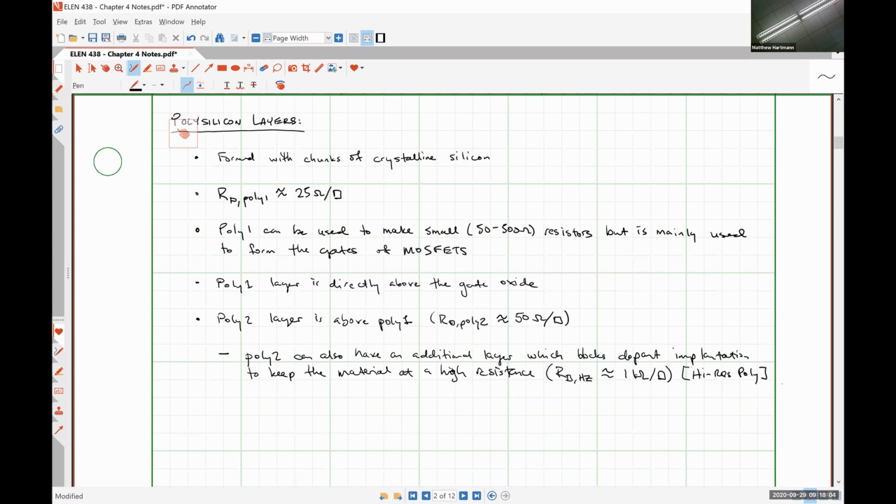In digital designs, the value of the resistor itself is usually not so big of a deal, but when we're trying to make an operational amplifier where we're going to have to do specific feedback configurations and all this kind of stuff, and size resistors very specifically so that our bias points give us the most amount of headroom, having a precision resistor is going to make the most sense.